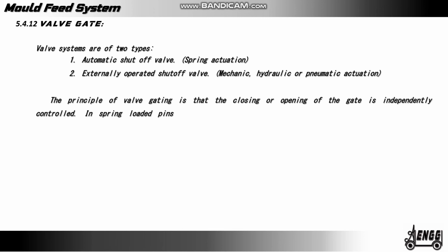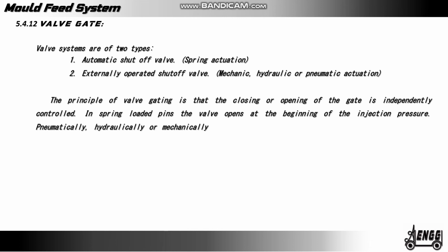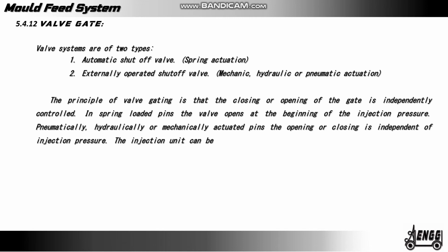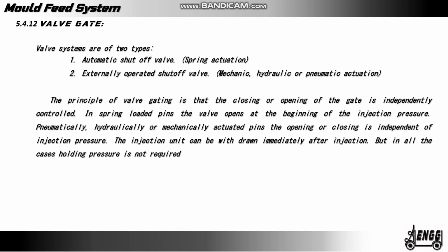With spring-loaded pins, the valve opens at the beginning of the injection pressure. With pneumatically, hydraulically or mechanically actuated pins, the opening or closing is independent of injection pressure. The injection unit can withdraw immediately after injection, but in all the cases, holding pressure is not required.